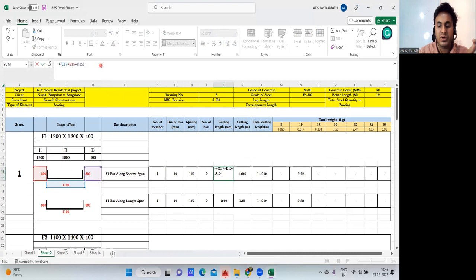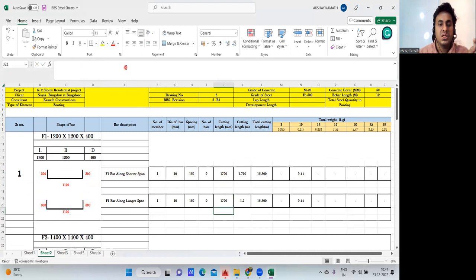Bend detection is not required, so criteria number one is satisfied. Second, this thing you say you apply 2/3 the depth. So 2 by 3, if you do, it will be 200. Accordingly, you see your cutting length will be this time 13.5 and 8.33, 8.33. Previously it was something like 9, so hardly there is any difference now.